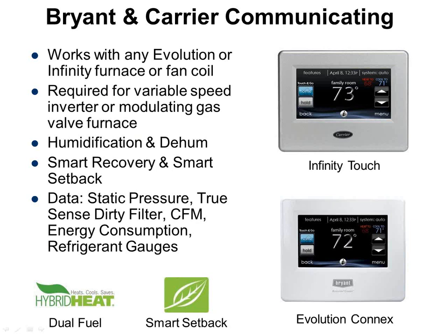In addition to smart recovery, it has something called smart setback, which basically means that even though you might have told your furnace to maintain 72 degrees during the occupied mode and 65 during unoccupied, you may come home early from work one day and see that your furnace is running and it's 67 or 68 in there.